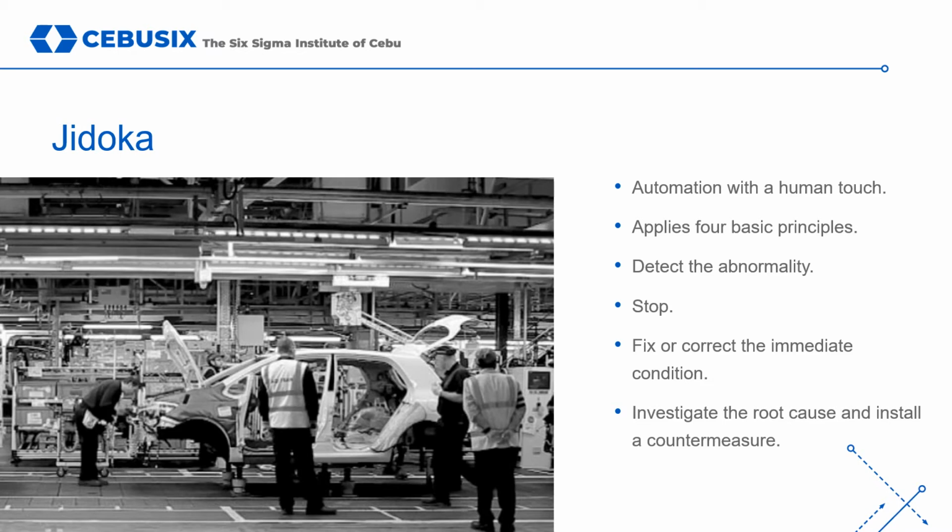In using the concept of Jidoka, as soon as we detect an abnormality, we need to immediately stop the process to prevent any further reoccurrences. We fix or correct the immediate cause of the abnormality. We basically put a band-aid on it. Then after we restart the process, we investigate the root cause and create a permanent fix for the issue.